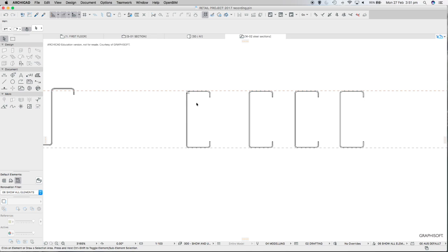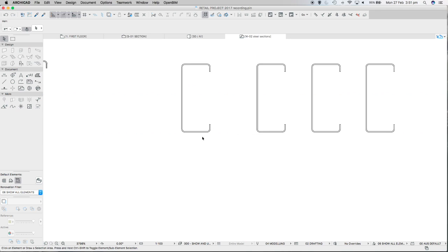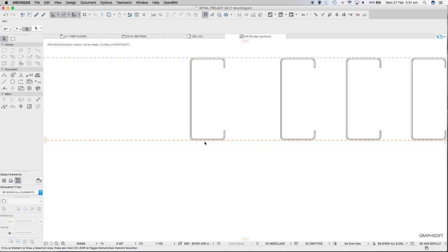Depth of a fascia in this building, look, I'm not too sure what it needs to be. We'll work that out a little bit later. But probably it needs to come down 50mm more at least to make a 200 deep fascia. So as a starting point, that's what we're going to do. I think we're going to be able to do that by, well, I'll just quickly measure that depth, by the way. Well, that's 152. So what I might do is I might move this top guideline, or make a copy. In case I need to use it later, I'll make a copy. So Control key or Option key, and come down the distance of 200 and press Enter.